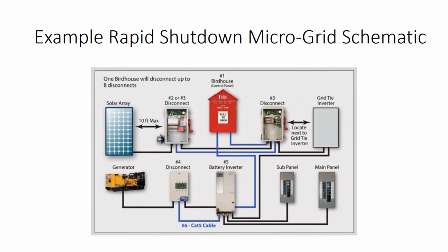Well, then we get to battery banks, and we say, well, now wait a minute. If my battery is designed to make me not lose power when there's a grid failure, how does that relate to rapid shutdown? Because won't the fire department show up to my house because my building's on fire, pull power to the property, and their concern is that you have these live wires from the solar array going outside the array perimeter. And so if my battery bank turns the solar array back on, now they think the power's out, but my backup system is clicked back in.